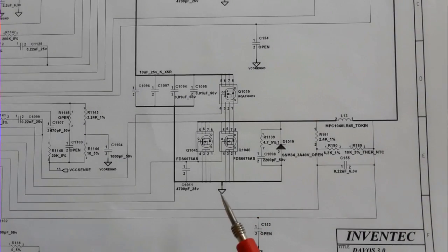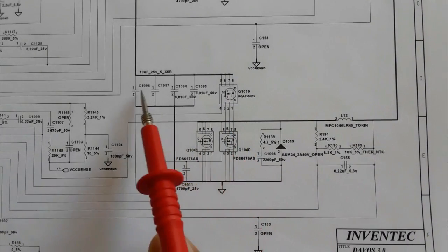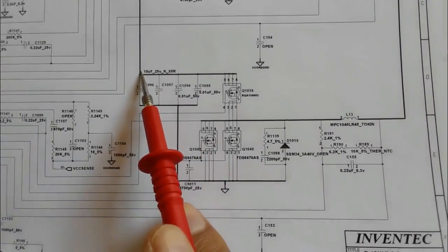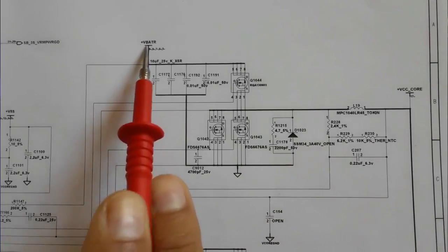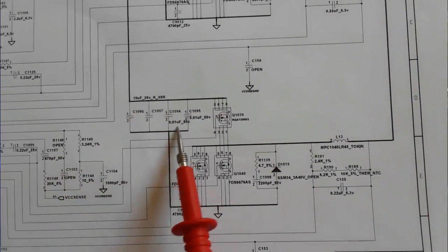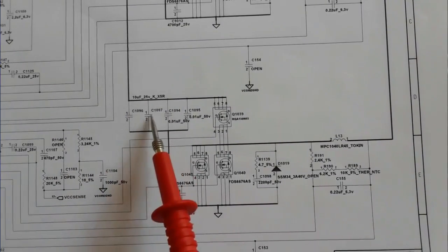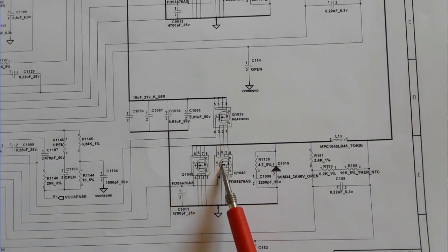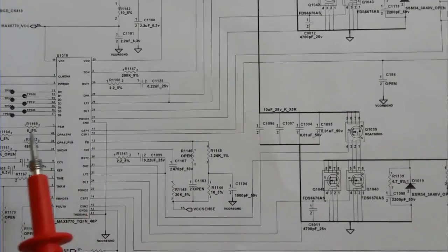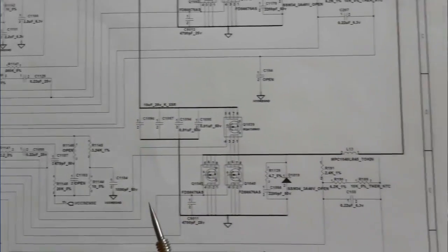The same here, as you can see, we have these MOSFETs. This is the gate. These 3 MOSFETs are activated by the power management IC. Here we have 4 ceramic capacitors. They receive the plus VBAT, the same as the first channel. The plus VBAT is always 19 volt or 20 volt. And after receiving the control signal from the power management IC, they will generate the VCC core. So this is the power management IC that generates the control signal for all MOSFETs.